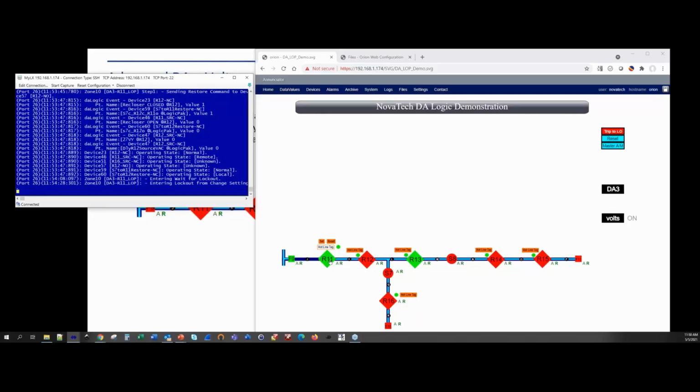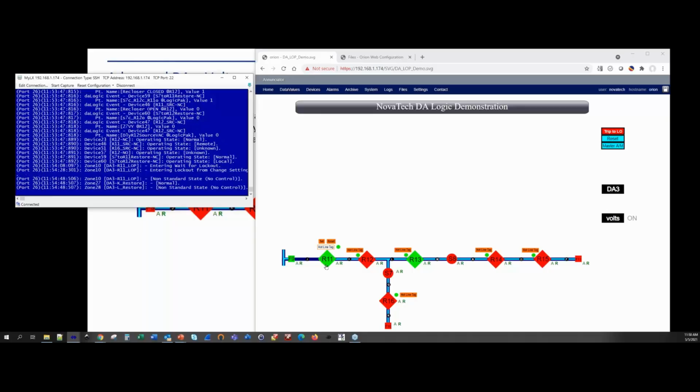So when the recloser is looking back to here, because it can't get any information from that, it might close in on a fault that's downstream of feeder F9. So the loss of potential logic simply stops right here. So the DA is complete for what it can restore. I did it one step at a time.